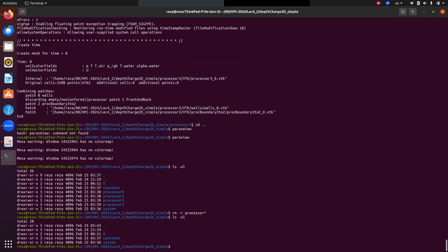So without parallelization, without power decompose, first time we run code, and then we will run it with decompose processing, and we will see what the difference. So again, we keep the setup of the problem, the boundary condition, the initial condition, the properties same, just running to create the meshes and then solve the problem.